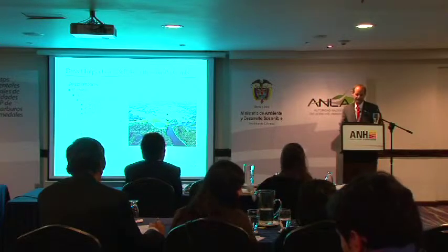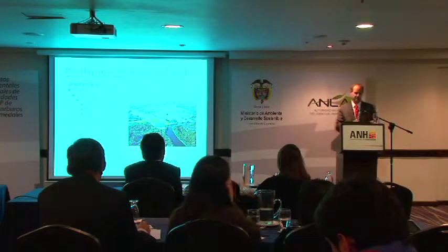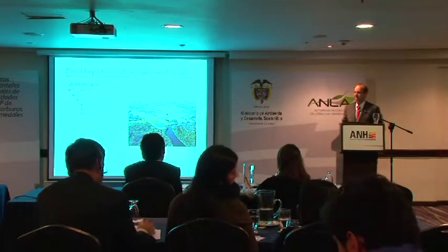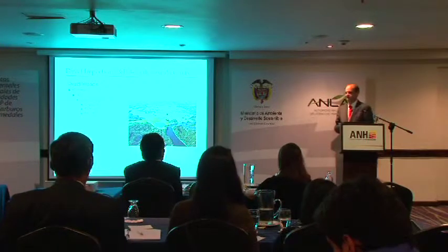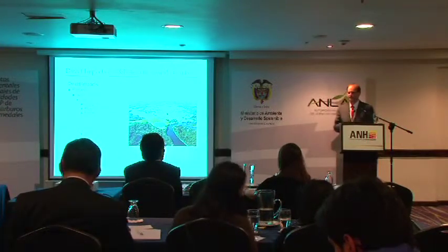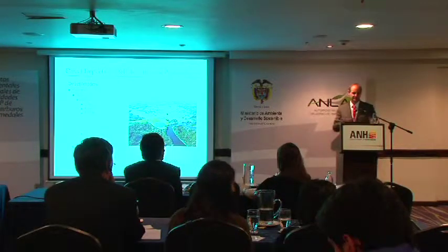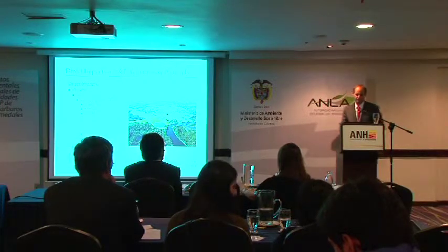When you channelize something, you redistribute not only the water, but you also redistribute the sediment, where the sediment goes. So you have increased sedimentation in some places. You have increased erosion in other places. And those two things vastly can change the dynamics and the processes that take place within a wetland.